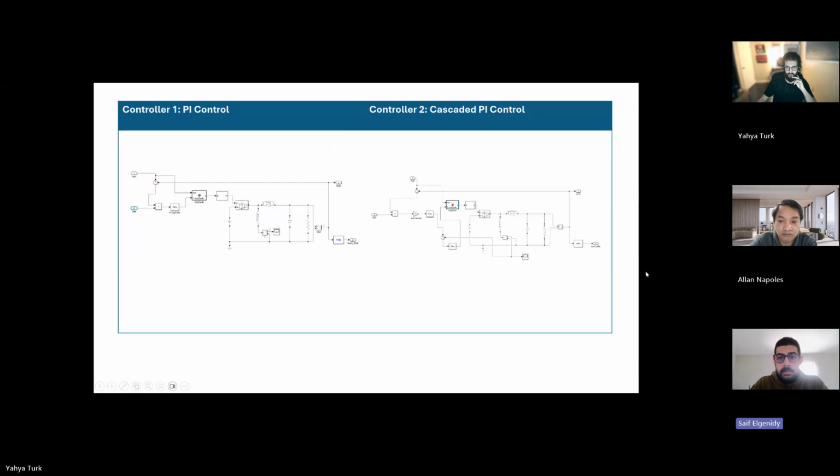In the outer voltage loop, the difference between the reference voltage and the output voltage is fed to the PI controller, which can determine the desired inductor current based on that voltage error, while the inner current loop adjusts the duty cycle by comparing the desired current that was computed with the actual inductor current that is measured across the inductor. So here it is cascaded because it is a 2-loop approach, 1 loop and then the other.